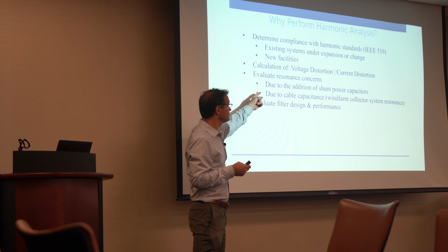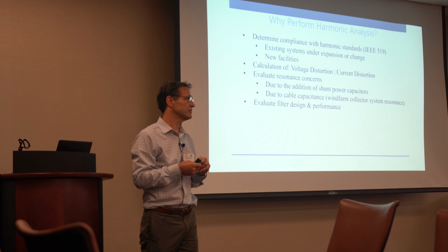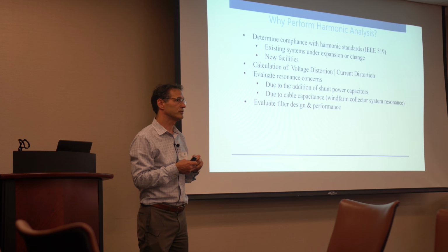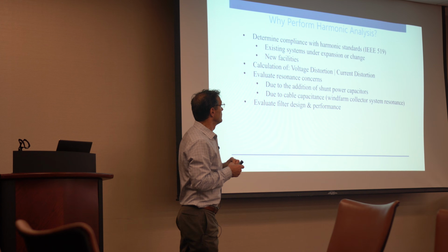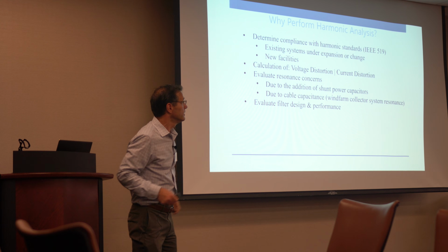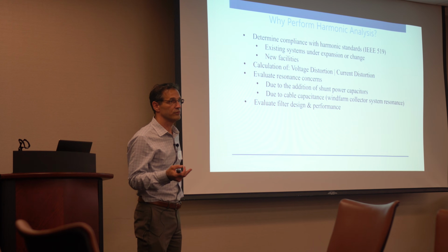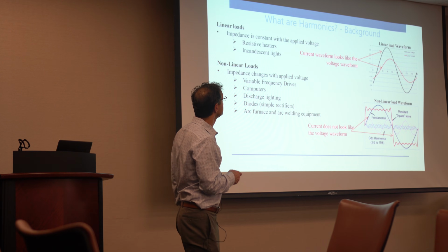You also have resonance concerns from cables, cable capacitance, an issue that's common in the wind farm industry. Just the cable capacitance alone can cause a resonance concern. So you're doing a harmonic analysis for that reason. And then finally, if there is some type of harmonic problem, you want to evaluate your filter design. So that's the reason you're doing it.